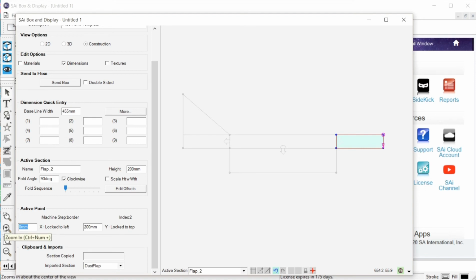I'm going to type in my 220 and then minus 55. You can actually do math in the control field here. And so when I hit the tab key, you'll say, oh no, it went the wrong direction though. Well, I'm going to just go back here and put a minus sign in front of this, so that will set it in the right direction. And now I have my two sides.